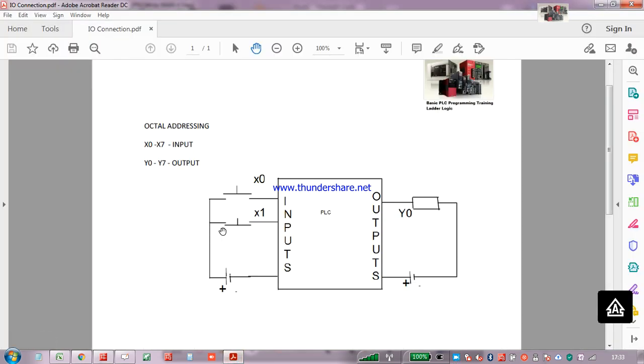Okay. Now we need to turn the motor off if we press the X1. Before putting it, you need to think that X1 is wired as an NC element. So we will get the input always by default.